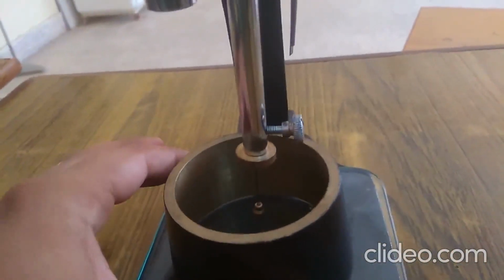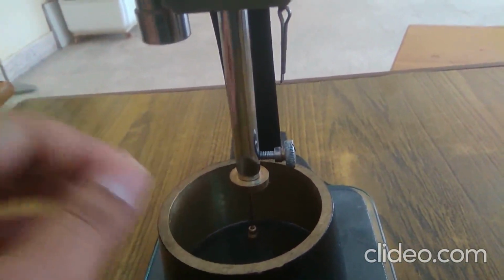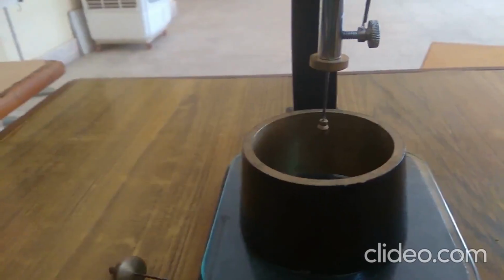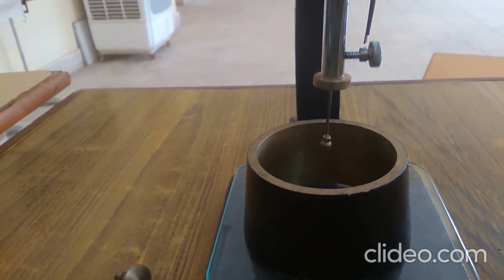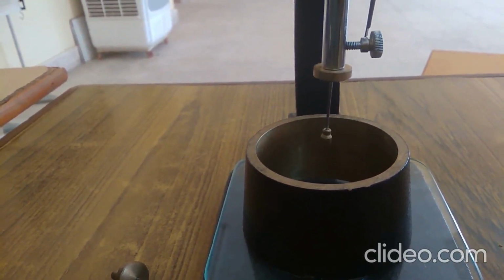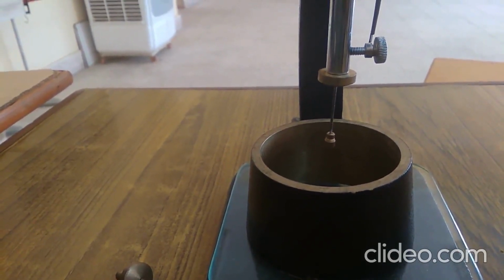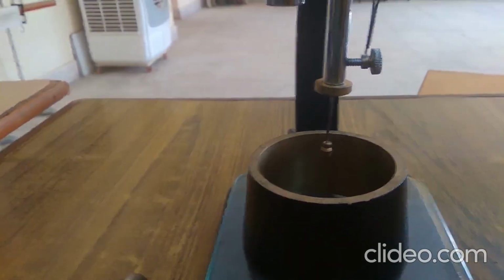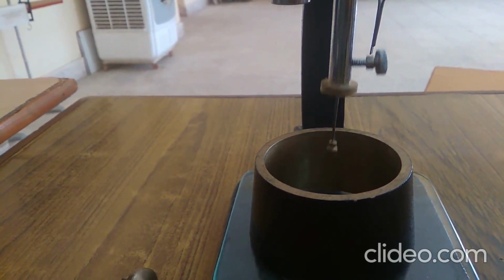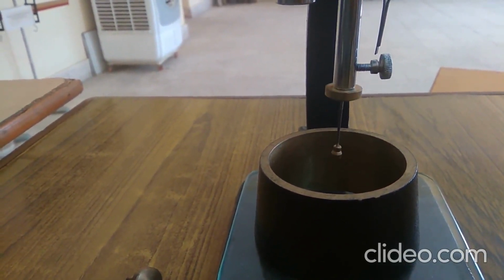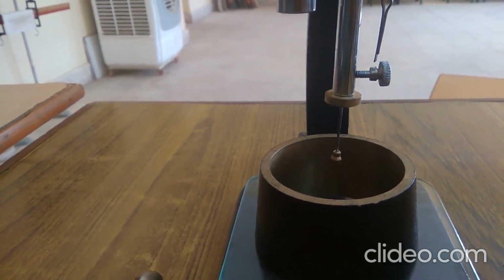So suppose this is the mold, this is the cement block, and we'll suspend this over the cement block to see the impression over the cement block made by this annular collar needle. We'll suspend this like this, and we'll note down the time.